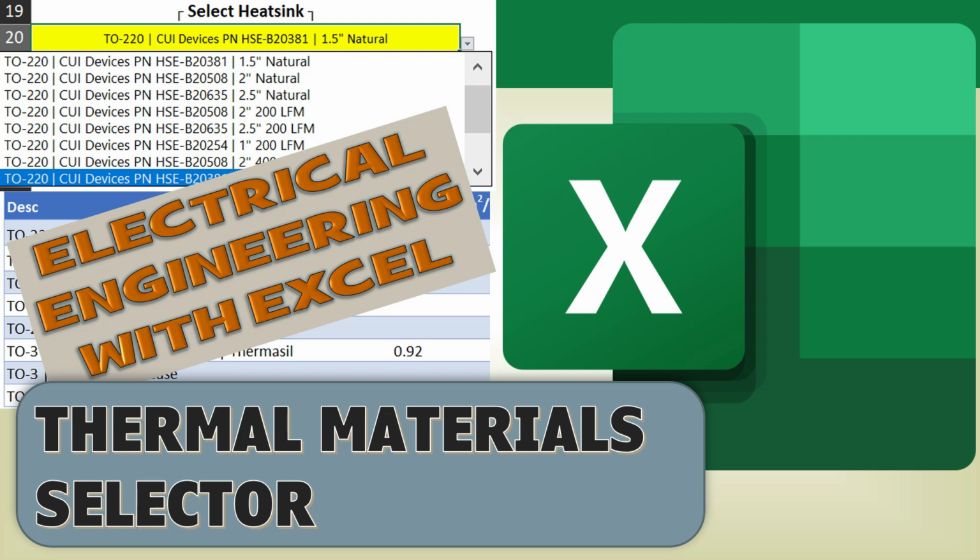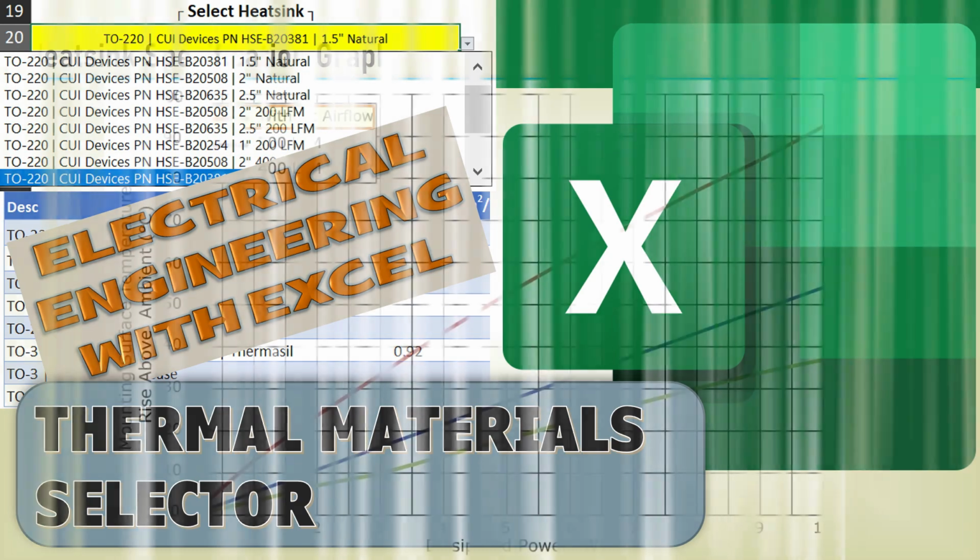In this video, we will take the spreadsheet we made for semiconductor thermal calculations a step further. Instead of manual inputs for the heatsink and the thermal interface material resistances, we will make a drop-down list selector that calculates or selects the resistances from tables. It uses the powerful features of Excel tables.